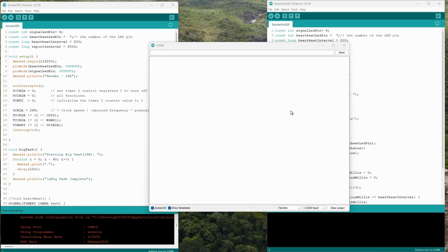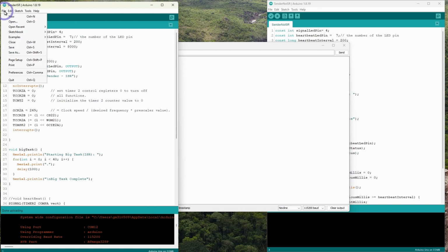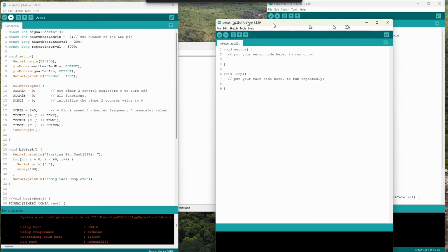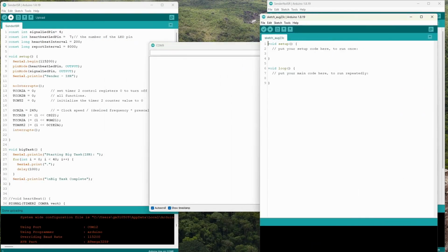Alright, so let's build out a receiving module for our simple little tamper resistant signaling device. And I think we'll start off with a new one, a new program. So to start off with, I'll just declare some constants. Okay, so we'll have the LED connected to pin 7 and the incoming signal will be on pin 2. So let's initialize those.